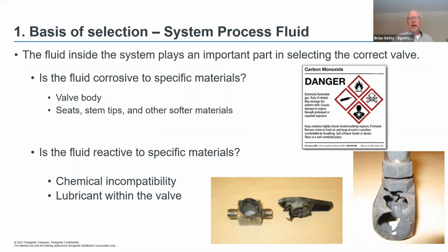What I've included on this one here is a couple of photos. You can see a couple of valves here which have been seriously damaged. This particular valve here was a ball valve. It was installed into an oxygen system, a system with a very, very high concentration of oxygen. Now, oxygen doesn't like abrupt on-offs in the system. So a ball valve in a high pressure, high concentration oxygen system is really not advised. Definitely try to stay away from that.